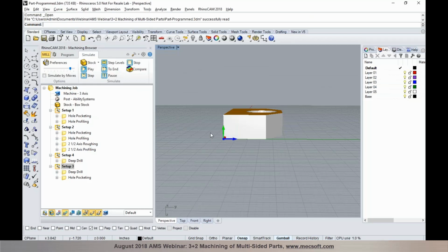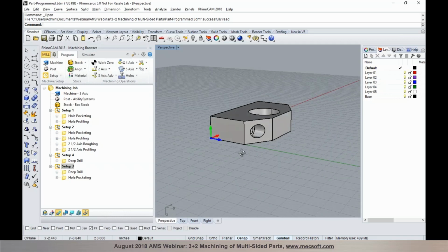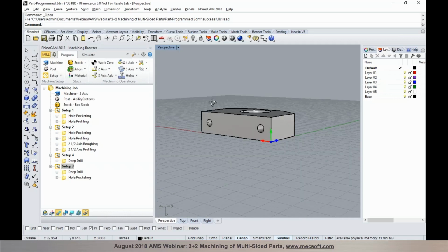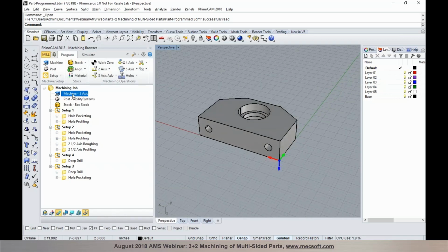Now, the last thing I would like to cover today is the post-processor considerations and how we can configure the post-processor to output the primary and the secondary angles, and how this is done in our post-processor in here. To cover this, I'm going to basically use the same example that I have in here.